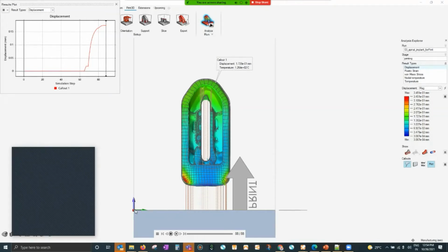So you may actually have to machine the base plate itself to remove it, or use some wire cutting, and that may in turn reduce the quality of the base plate itself. So that's why there is a standard practice to leave a certain distance so that a little bit of support is created, and these supports are weakly created so that you can remove them easily, right? So that is the reason.